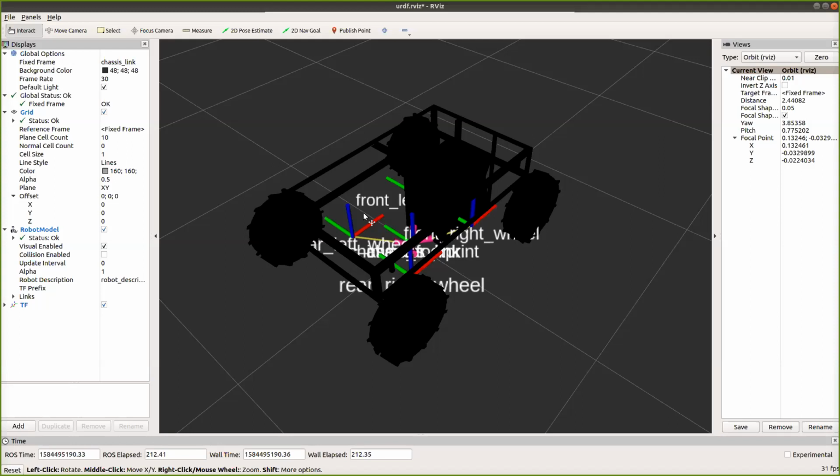But sometimes I haven't had a local network that I can reach when a tractor is off in a distant field, and RViz has some real problems with that. It might be because of stamped headers and timing, and it just throws them away. But yeah, if you're doing visualization, just be careful with that.